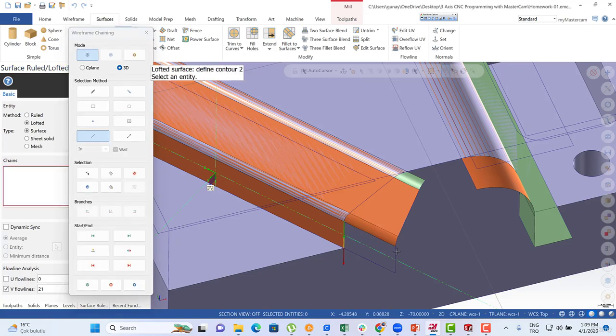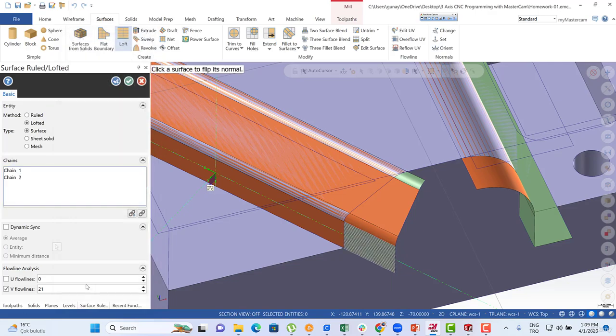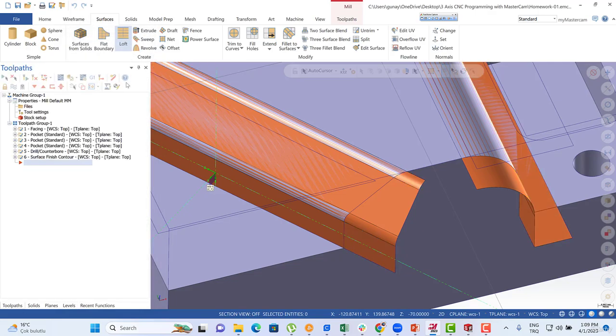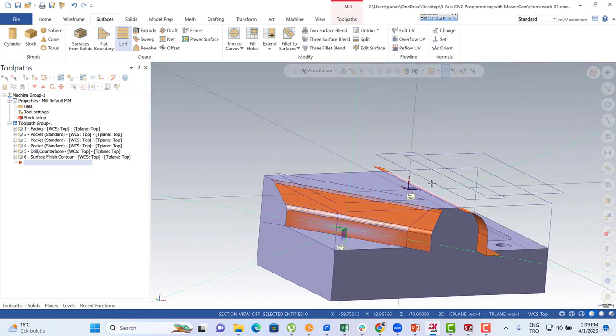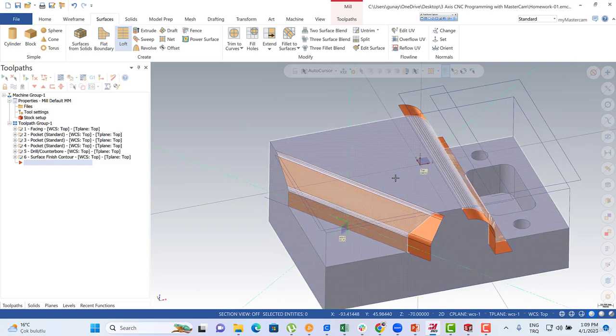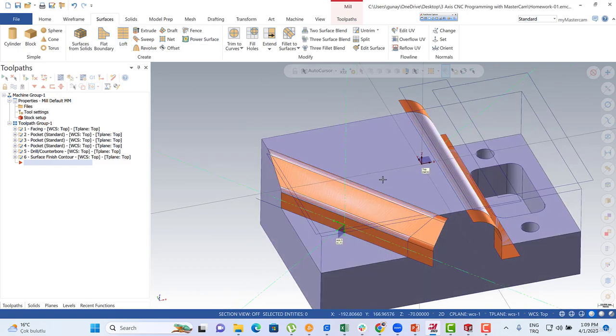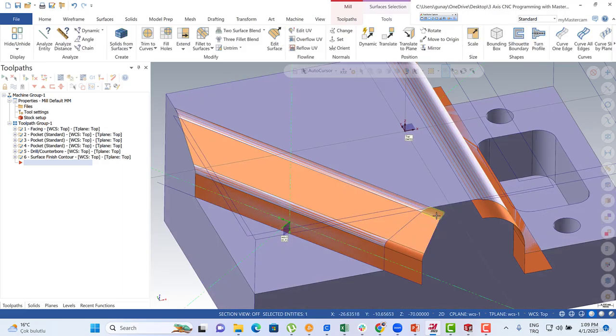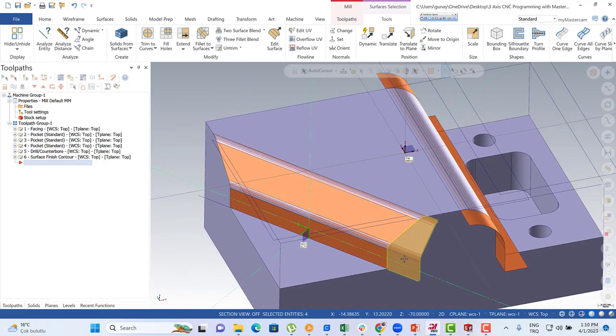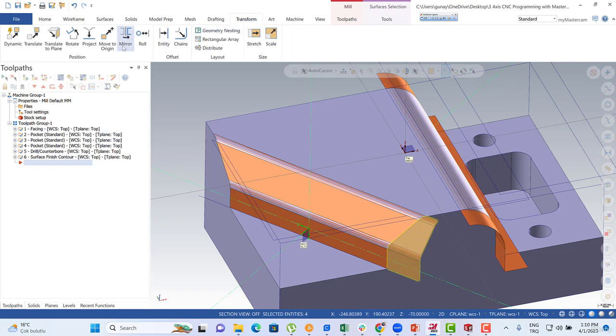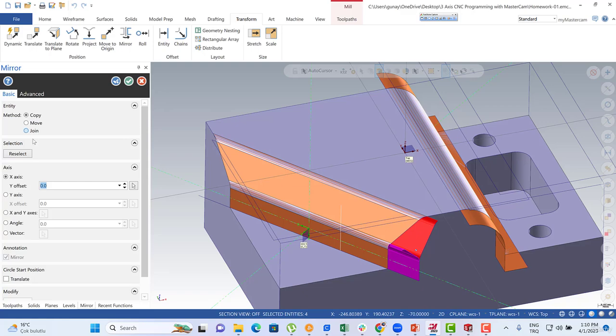We can select this one and this one as well, and then you're going to see that kind of face here. Okay, and according to this perspective, let me select all those faces, this one, this one, this one, and this one, and then I can easily use the transform and mirror options, and according to the mirror options, we can prefer to use the X-axis.